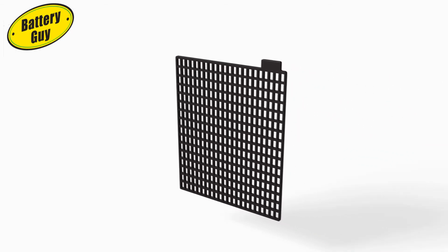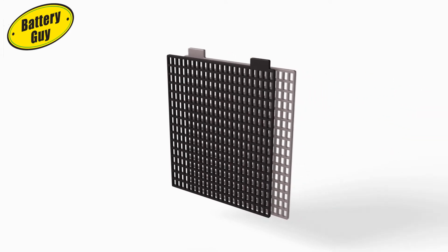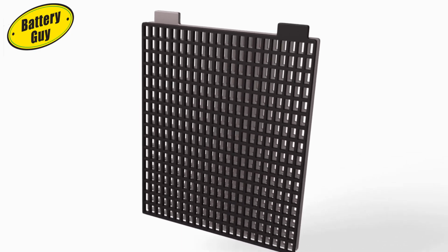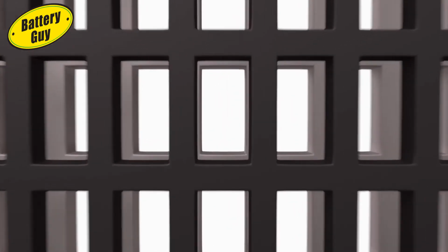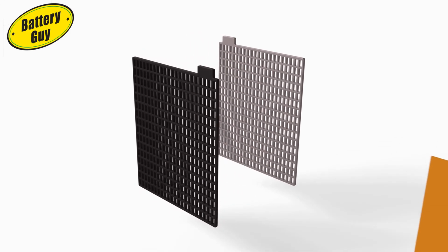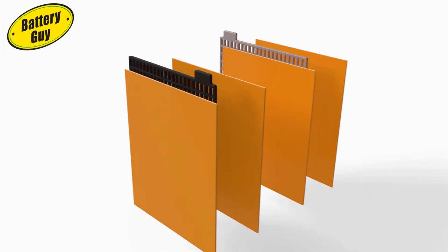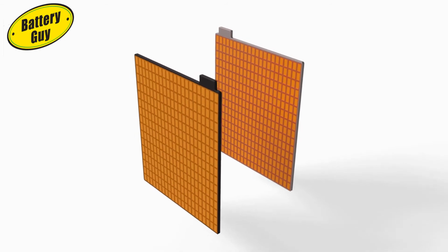The process starts with a lead alloy cathode and a lead alloy anode. They are usually manufactured as meshes to maximize the surface area of the plates. A greater surface area means more power per plate. A paste of lead oxides, sulfuric acid and water is applied to the plates, which increases their effectiveness. Without this, the power they can supply is limited.